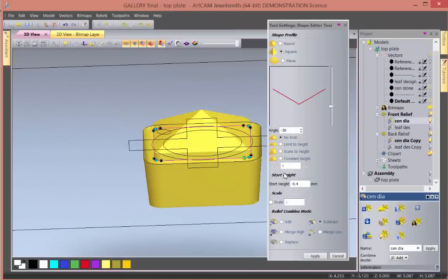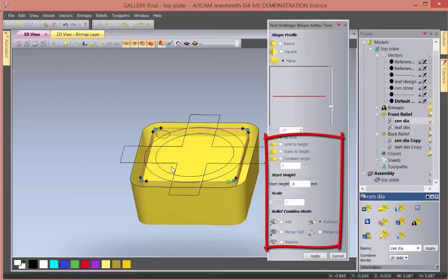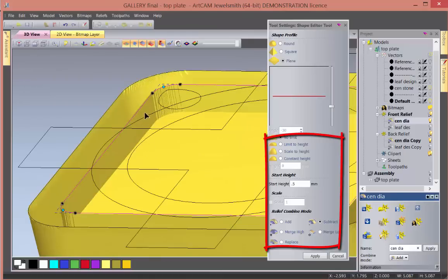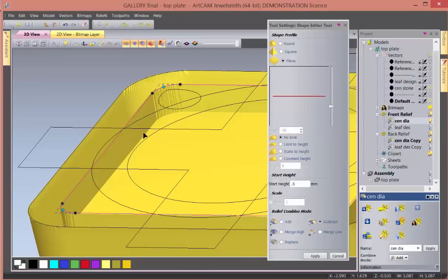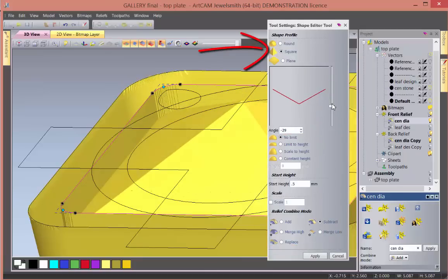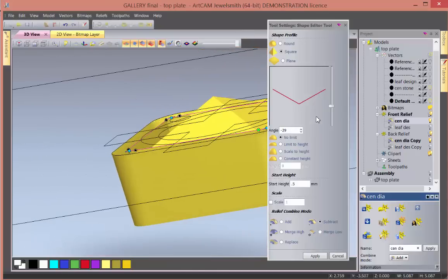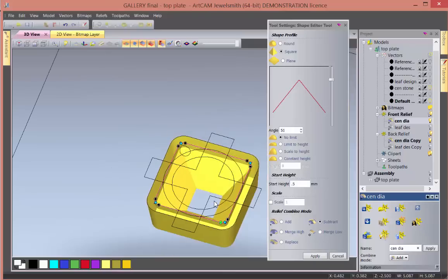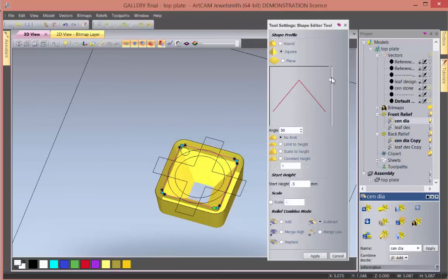So let's bring up the shape editor. The shape editor normally starts off flat. I'll put these values onto 0. So this is where we normally start off. First of all, we want to go 0.5 and subtract. So it's going down. There's our 0.5 going down. And then we want to introduce an angle, so we can have a square angle, and now this angle is going up. But that's okay, it's working live. If it's going up, you just reverse this, and you can start to see it introduce this angle going all the way down.